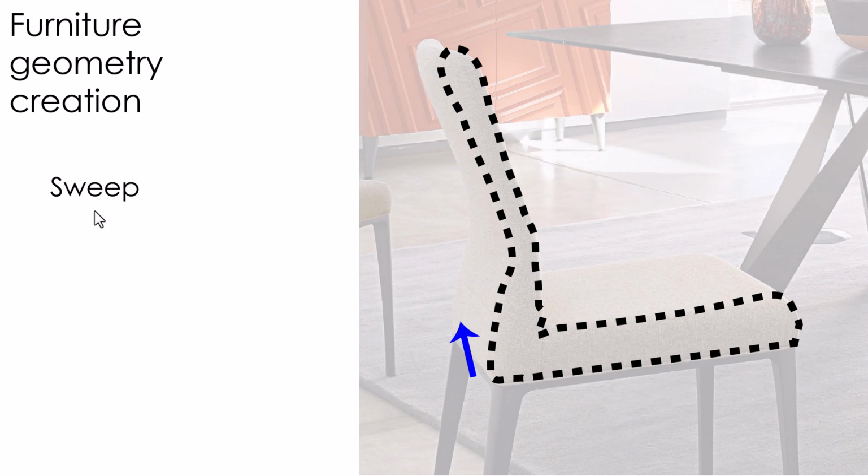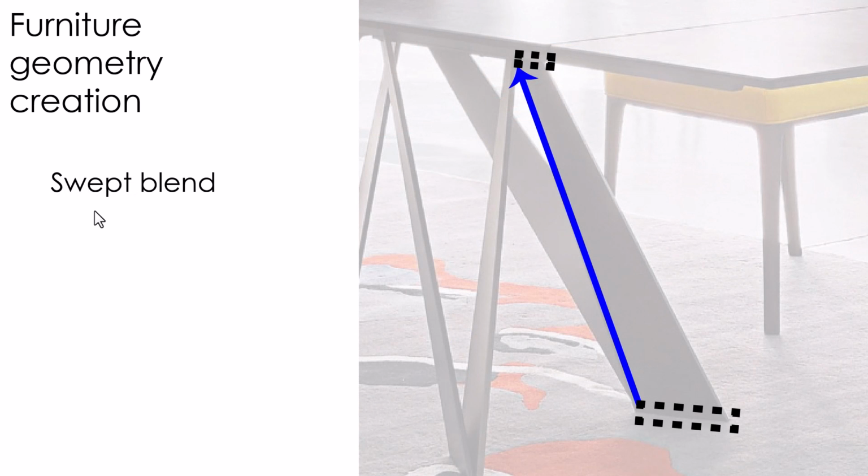So, once you've considered all these shapes, now take a look at what you have to model. Again, I'm going to start with furniture because it has some of these primitive shapes. If you want to create, say, the back of a chair, if you just draw the dashed line here as the profile of the chair and just create a path for it to extrude. I guess it's actually not even a sweep, it's really just an extrusion going off in one direction. I suppose if you want the curve on the back of the chair, you'd have to add one extra little piece to it. But once you can identify the geometry of this chair seat, it's pretty simple, really. You do have to draw it.